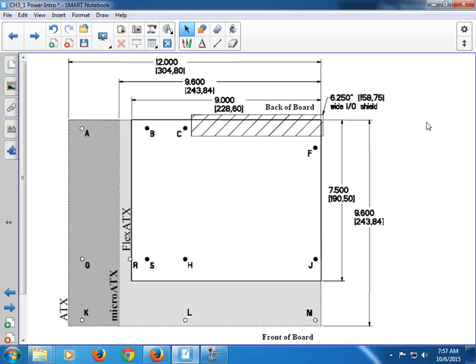In fact, you can get one that's as small as just those 4 screw holes there. And then as you get bigger, it adds these screw holes, then it adds these screw holes here. So when I say it's a full-size ATX case, it means it has spots all the way out to here to screw in my motherboard, and standoffs work too, so it doesn't sit on the case. Okay, and a standoff is a little screw that holds the motherboard off the case.